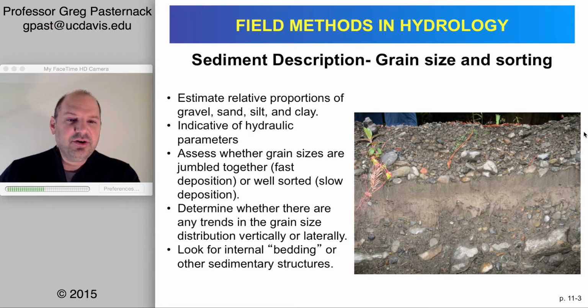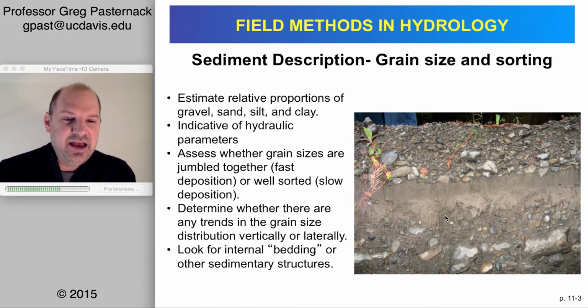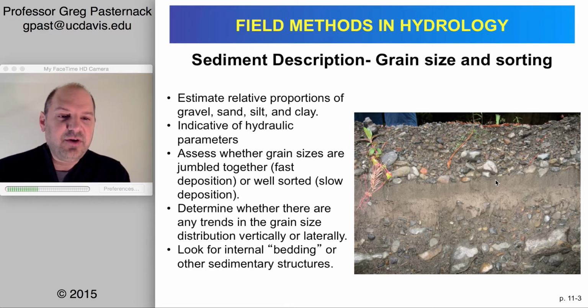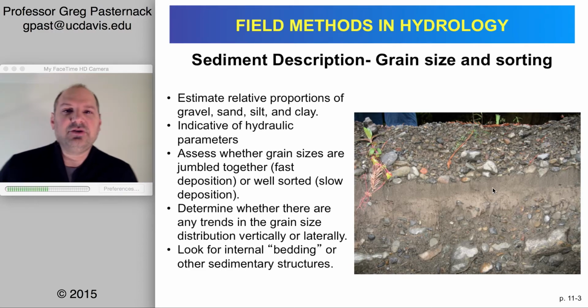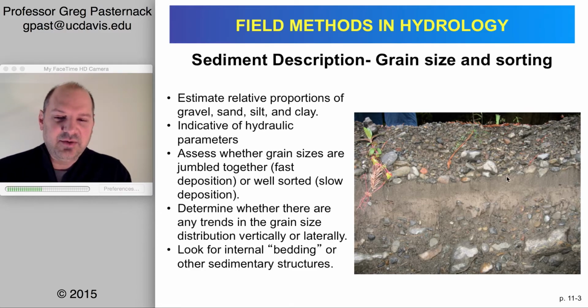Also, if you look at the pattern of the sizes that are there, like if you look in this photo, you can see distinct bodies of sediment in here, which people call packets or strata, and they are representative of different hydraulic conditions that led to the deposition that you see there. So trying to reconstruct what those conditions were can be very important, and so being able to characterize those sediments as a first step, and then understanding the science of what that means, which is a part of the geological fields of sedimentology and stratigraphy, then you can really make a lot of headway as a hydrologist.